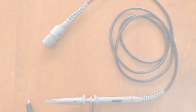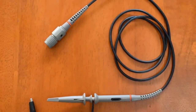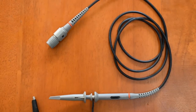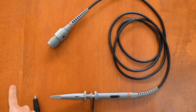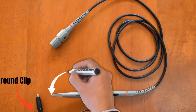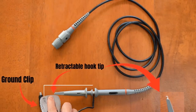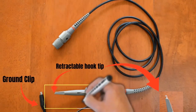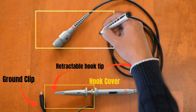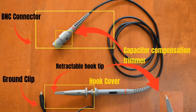As it turns out, scope probes are more than just some pieces of wire. The most common probes you will find are passive voltage probes, which means that they measure the voltage difference between the round clip and this retractable hook tip. The hook is covered with a cover. To connect the probe, we have a special connector called a BNC connector. And there you find the capacitor compensation trimmer. You will see the need for that later when we go to the practical.